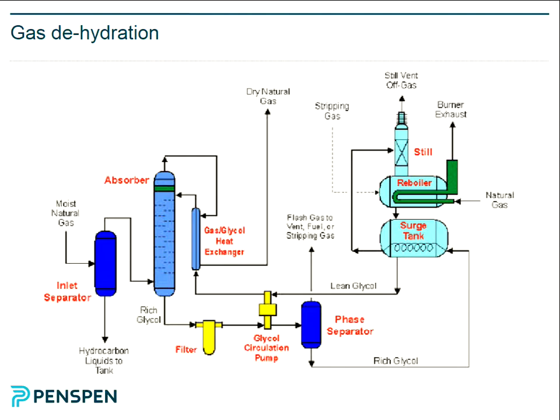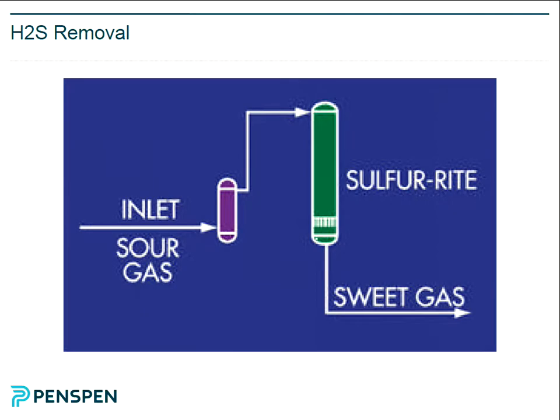So this is the location of processing equipment. It's very much down to economics. If you produce product from a reservoir, if you can avoid a platform completely and go all the way from your subsea development to the shore, then that's perfectly feasible. But generally speaking, you can't do that because you need to treat the gas. You'll get hydrates. There isn't enough pressure driving force to get it all the way to the shore.